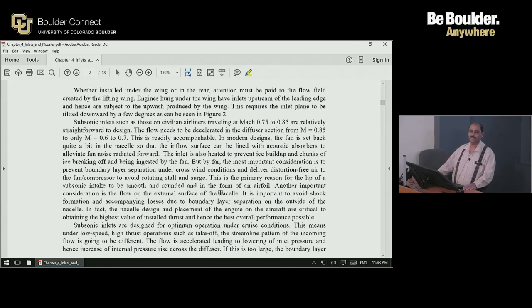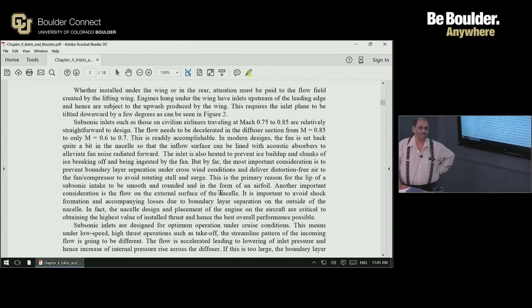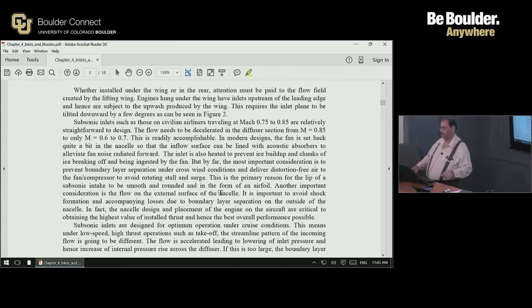After that is done, the engines are supplied to the airframer, they mount them on the aircraft, and then they put the aircraft through a variety of required certification tests. Usually, roughly about half a dozen engines participate in the certification process. And usually 3 to 4, maybe 5 aircraft, depending on how quick the airframer wants the certificate, participate in the certification process.